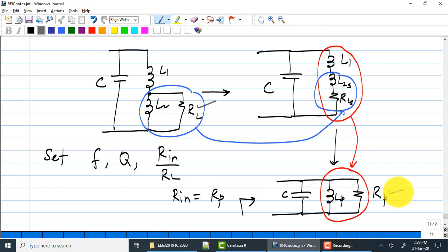So the easiest things to find, you start with the parallel resonant network, the simplified network. You know RP, the input resistance is RP, that has to be equal to Rn. So since you know Rn, we already know Rp. Correct? Do you know the Q of the network? Of course you do. So you can directly find C and LP. So Rp is equal to Rn.